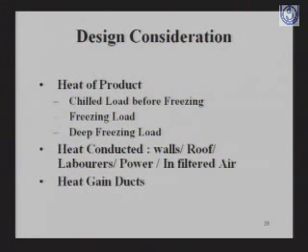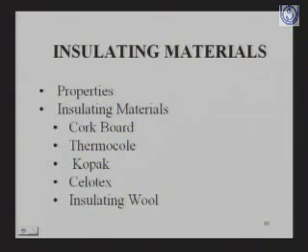When we design the cold storage, what type of considerations do we keep in mind? We consider the type of the product. Then based on the product we see what is the load before freezing, what is the freezing load, and what is the deep freezing load. So heat conducted through walls, roof, laborers, infiltrating air, then heat ducts. Based on these considerations we design the cold storage and its refrigeration capacity.